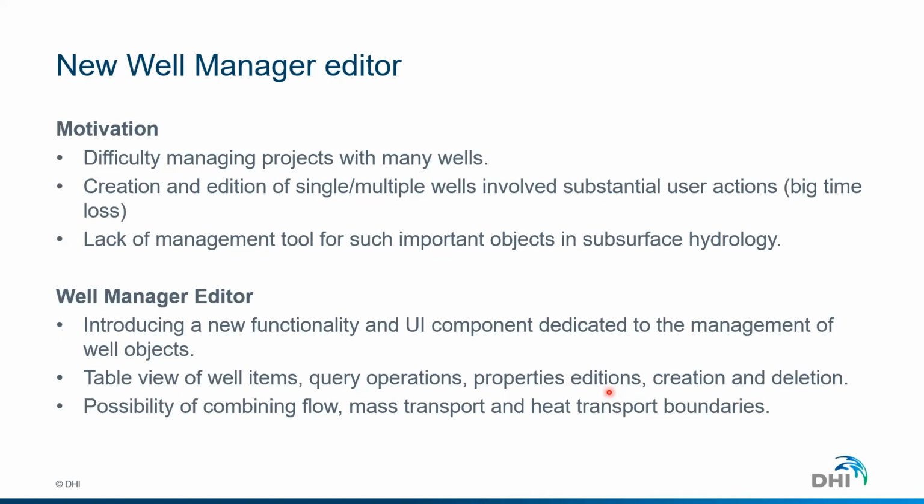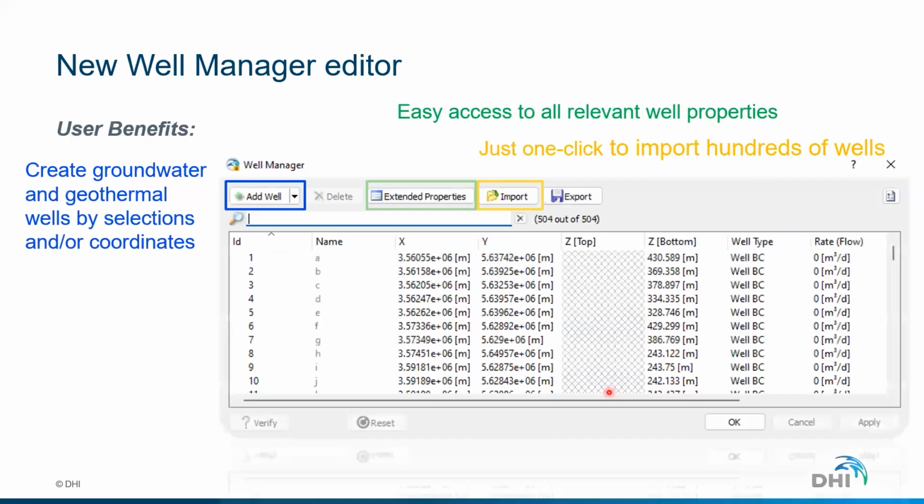Wells could be combined with flow and mass transport, and flow and heat transport boundary conditions. Everything is quite clean through a tabular view. You can do some operations like queries, so you can filter wells based on time series, names, etc. It looks like this, quite simple. We actually made it really simple on purpose. You can also import your wells, which come from Excel or any supported file formats, and in a couple of clicks you have hundreds of wells in your FEFLOW model.